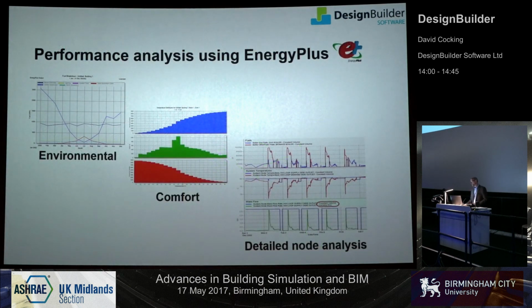All of the normal stuff you'd expect from an engine like EnergyPlus, environmental comfort, detailed node analysis. We've got a results viewer tool that enables you to drill right down to the nth degree, look at every time step, what's happening at every node in that detailed HVAC system, for example, and do comparative analysis on multiple simulation sets.